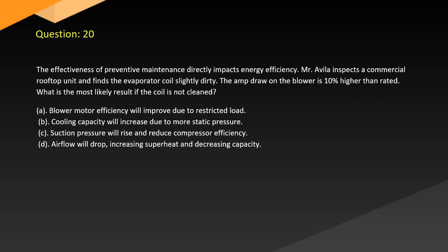Question 20. The effectiveness of preventive maintenance directly impacts energy efficiency. Mr. Avila inspects a commercial rooftop unit and finds the evaporator coil slightly dirty. The amp draw on the blower is 10% higher than rated. What is the most likely result if the coil is not cleaned?